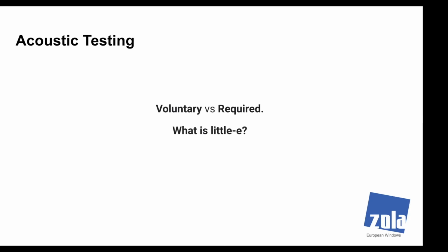There are certain corridors and certain areas of the city that are just loud. And if you're going to build residential, then you are required to have a maximum acoustic threshold inside the building once the building's completed. I believe it's 43 decibels RW.